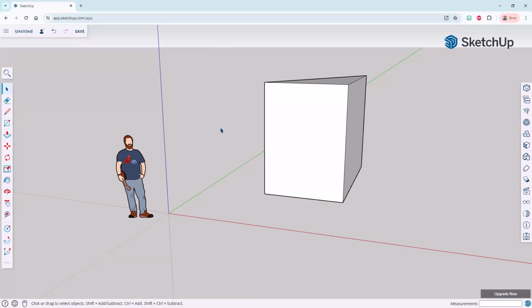And that is groups. I need you to understand this concept and apply it immediately. So what we need to do is, now that we've created this object, you'll notice how all of these are independent, if you will, separate surfaces, separate edges. There's even points here that I can pick, but I don't want to pick them individually. I've created this solid and I want it to act as a group.